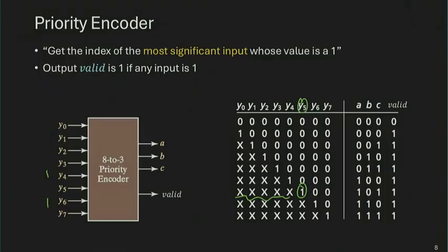And what we learned is essentially just a simple binary encoding and decoding idea based on the number of ones. For decoder, we have a 1-hot encoding at the output. For encoder, hopefully we have a 1-hot encoding at the inputs. But if not, we have a tie-breaking mechanism through this priority encoder so that the output remains valid.